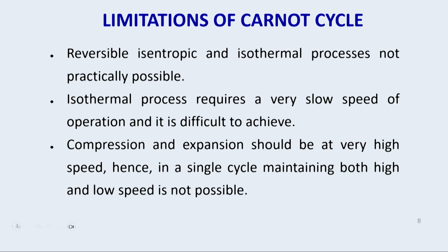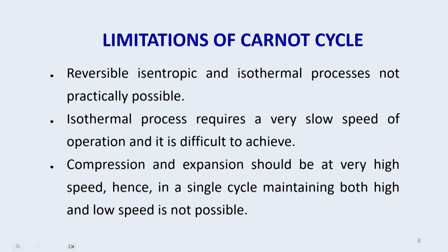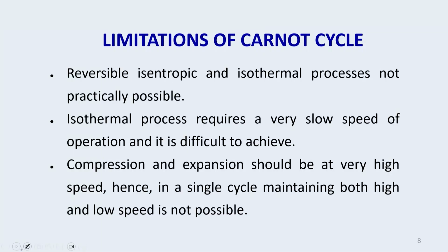So the next, the compression process, which is 1 to 2, and the expansion process should be at very high speed. Hence, in a single cycle, maintaining both high and low speed is not possible. Apart from these, there are limitations also. In the actual cycle, there will be losses due to friction. Friction will be there in practice. There will be heat loss, irreversibilities. So achieving a Carnot cycle in real-time processes is not possible.